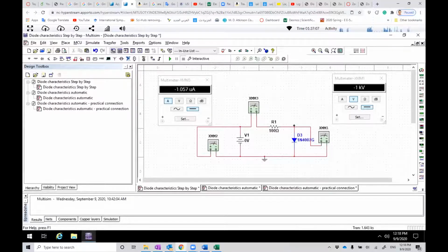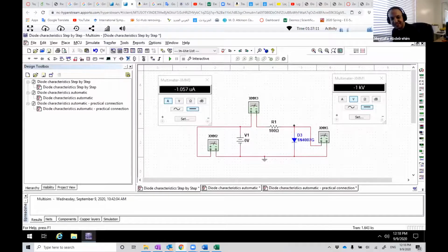Well, it's going to draw a large amount of current. Yeah, that's very large. Yes, it will be a very, very large current. And the reason is that here I am forcing. If I put this resistance, the diode will just take around 0.7 volts, and the rest, because of course Kirchhoff's voltage law.